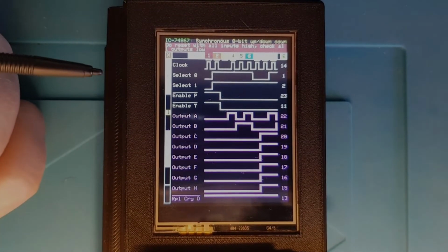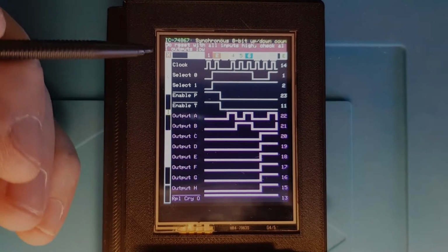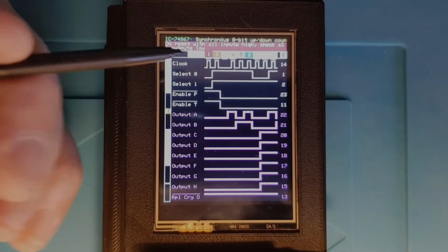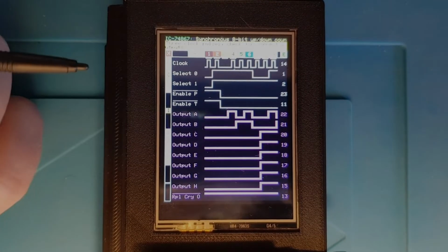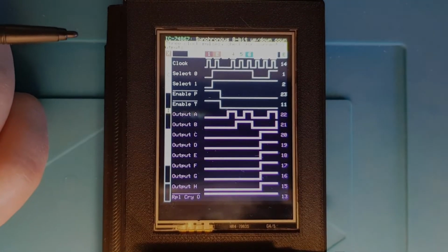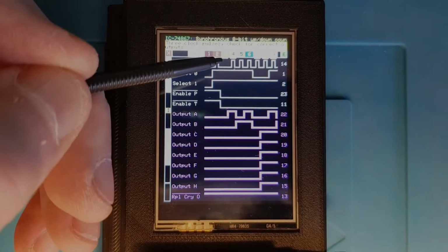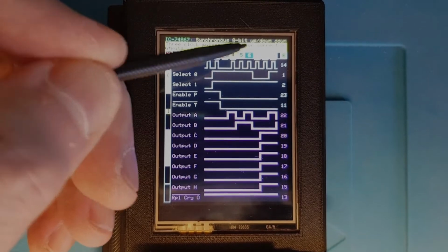So that first step there resets all the inputs, sets all the inputs high and checks all the outputs are low, right? And if we actually look at number 4, that shows 3 clock pulses and checks for correct outputs. Now that's going to take 3 steps altogether. That's 4, 5 and 6.